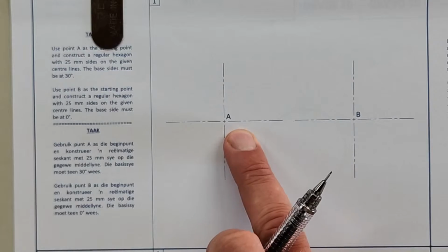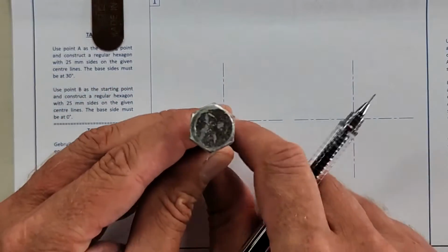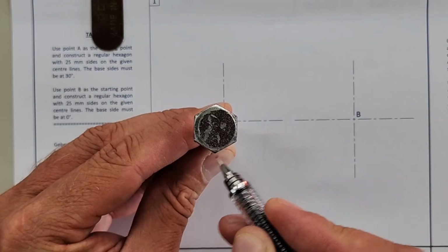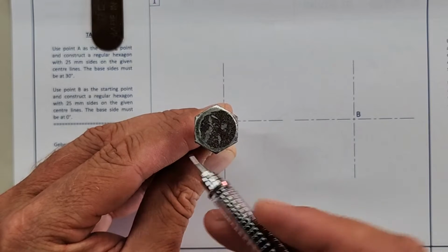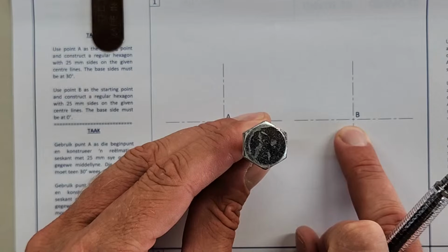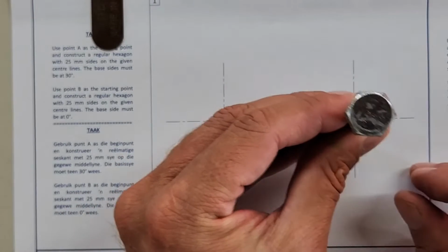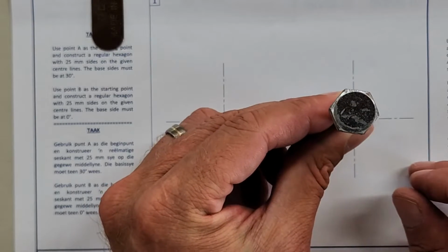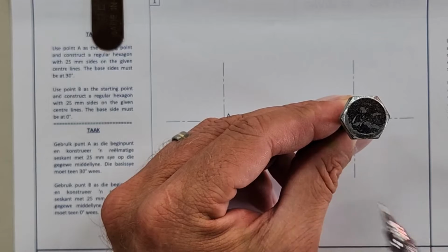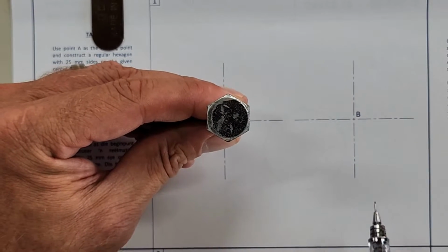So they're wanting us, if you just remember, this is now, let's apply it. In A, they want the base of this hexagon to be at 30 degrees. It means these 2 angles must be at 30 degrees. In B, they're asking us the base side must be at 0 degrees. So they want us to draw it in this position. Do you see the difference between the 2? We've got a base here at 0 degrees. It's parallel, horizontal. But in A, it is drawn as a 30 degree.